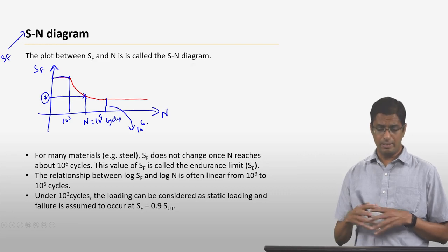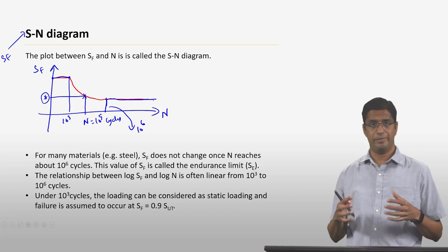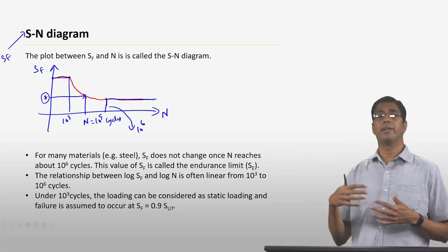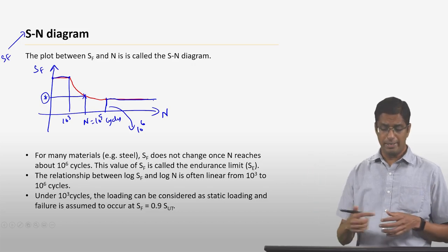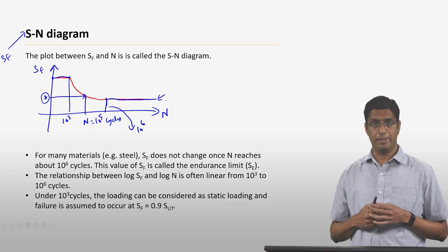As long as the stress that you apply is below this value, the material is not going to fail. Or the other way you can think of it is, if you go beyond 10 to the 6 cycles, you have to apply at least this much stress for the material to fail.